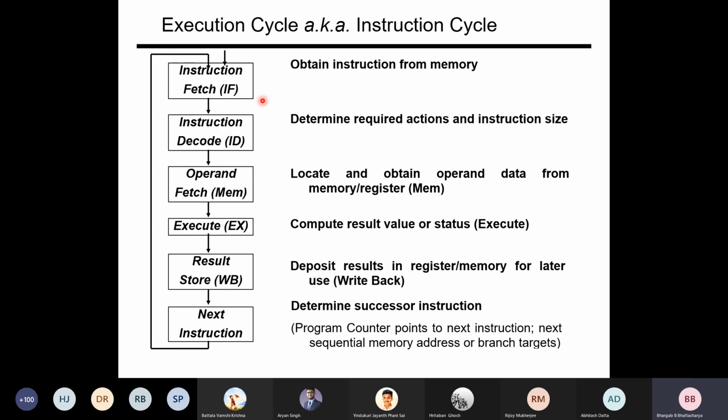In every stage there are registers or memory elements. When you fetch the instruction from memory, you bring it to the processor side, but you need to hold that value, right? So there are some registers called instruction registers, which save the current instruction, because you have to save the current instruction until the operation of the instruction is finished, right? In order to maintain those, you need several clock cycles which synchronize all transfer operations.